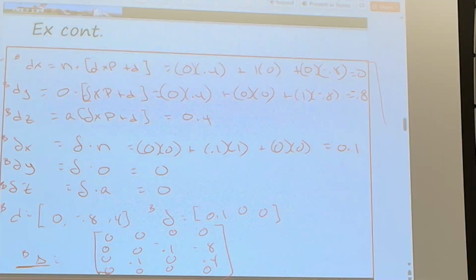Yeah, that's not too bad. And at any point in time, you have a Jacobian. Those values are constantly changing because they depend upon the theta combinations of all of the joints. Remember, it's partial to one, partial to the other.